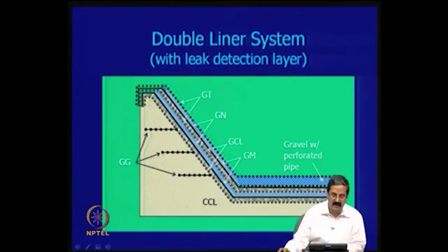The moment you put in a material like a geogrid and give some tension force, say 5 kilonewton per meter, it is all a tensile element. The software will tell you the factor of safety now is 1.4, it is fine like that, okay.